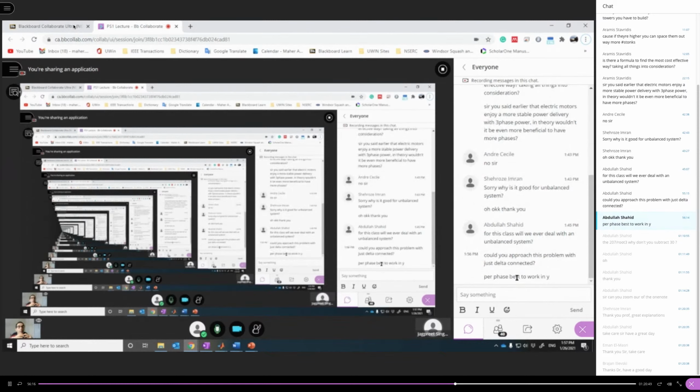Look, the idea here is to transfer the three-phase circuit to a single phase circuit, because we used to deal with single phase circuits. We cannot keep the delta connected loads. We have to switch them to star connected loads and then convert the three-phase circuit to an equivalent single phase circuit to analyze.